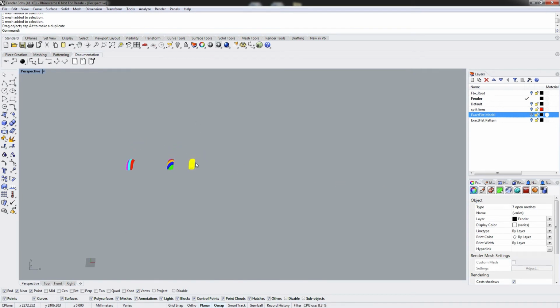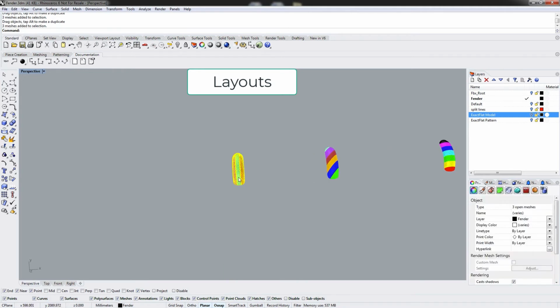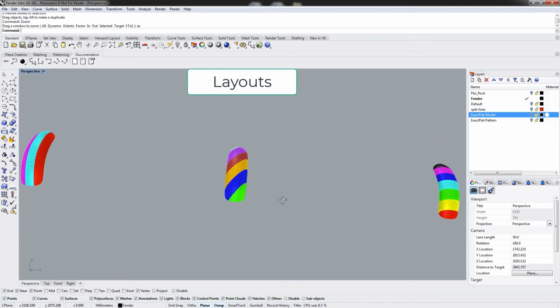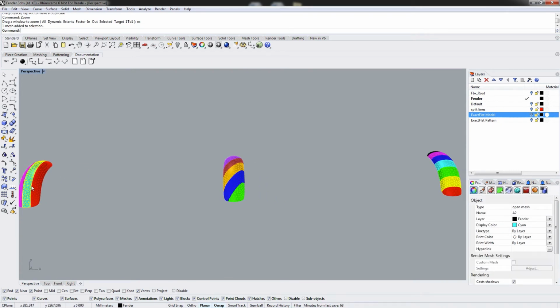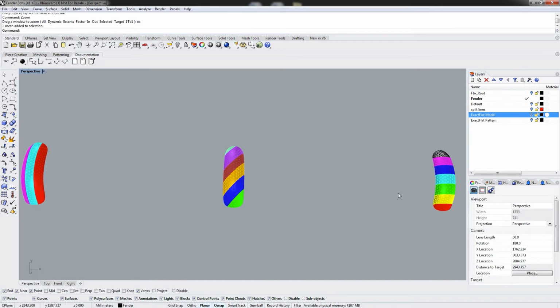We're just trying to create some physical separation between them here, and what we're going to do next is use Rhino layouts to create or insert pages into a PDF. We're going to use the actual model data here to act as our layup schedule or ply book. So we've got our 3 different layers from left to right. We've got our layer A1, 2, and 3, B1, 2, and 3, and C1, 2, and 3.